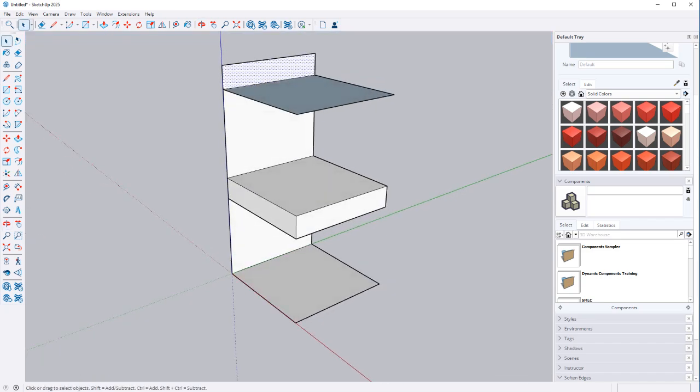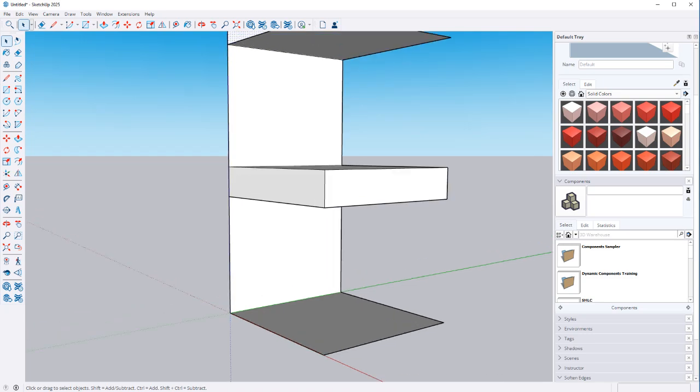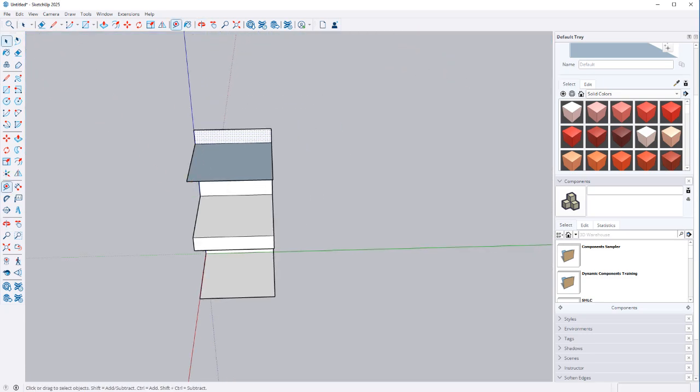If I'm trying to connect these two floors, what I need to know is the height from here to here, not here to here, because this just tells me how I get to the ceiling, but it's going to keep going up. Again, I use 2 feet as a generic number. You can get thinner, but it gets more expensive. At a certain thinness, you need to switch to metal instead of wood. It depends on the width of the space, and there are all kinds of engineering calculations, which are not really our problem, at least not for now. My rule of thumb is to call it 2 feet thick, and that's generally fine. You should never run into a problem.